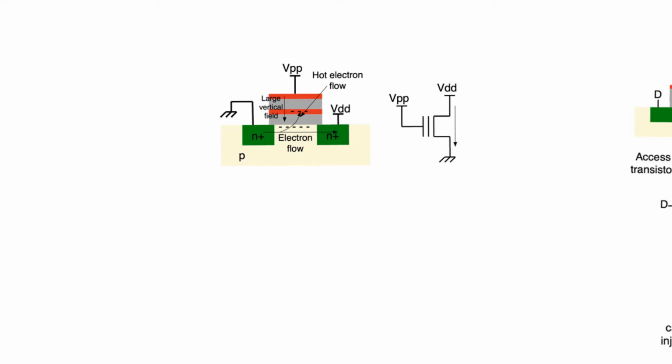The first kind of non-volatile memory we will discuss is EPROM, where E stands for electrically and PROM stands for programmable ROM. So this is an electrically programmable ROM, and it is specifically only electrically programmable, meaning that it is not electrically erasable. This means that we can program a 0 into a cell by causing the transistor to not exist by raising its V threshold in situ when the transistor is being used on the chip. But we cannot deprogram it or erase it while the chip is being used.